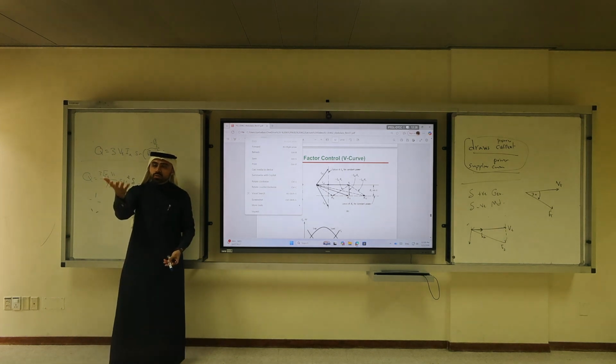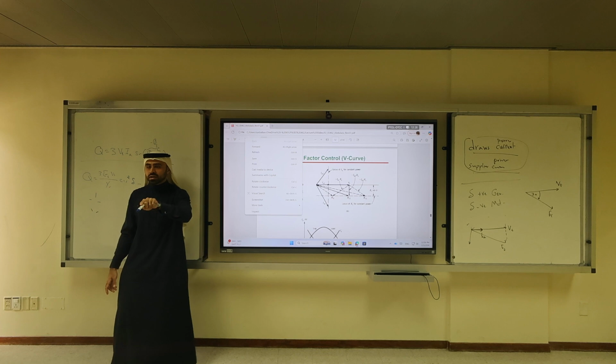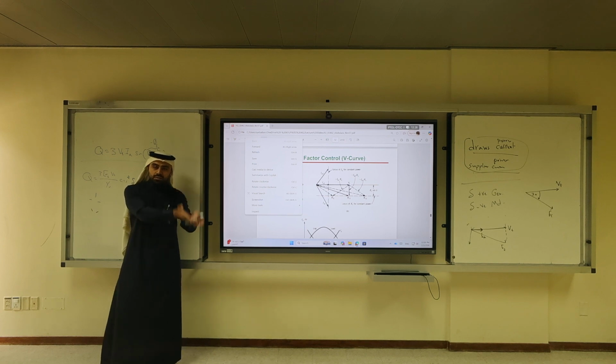So why do you always want to have a low torque motor? To reduce electric current density. Ultimately, we will see when we study the dynamics of the machine, the torque is correlated with the electric current drawn from the battery. The higher the torque, the higher the electric current. So your problem with EVs is not the motor nor the gearbox.